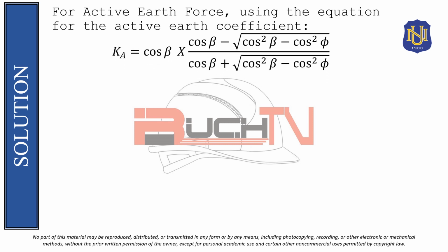So that is still Ka is equal to cosine of beta times cosine of beta minus square root of cosine squared beta minus cosine squared of phi, divided by cosine of beta plus square root of cosine squared of beta minus cosine squared of phi.